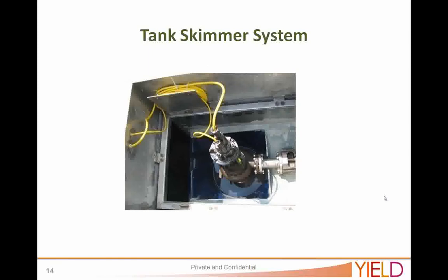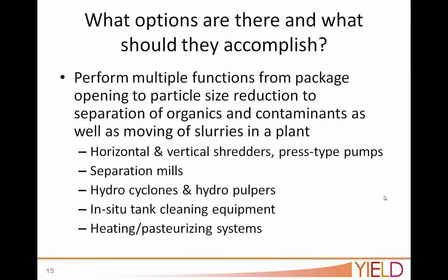And essentially all the digestate from the tanks passes through this skimmer and a filter. And so essentially every cubic meter that's put out of our system is essentially 100% clean. There is obviously still some grit fraction in there, but visible plastics are all removed, and you're into a small amount of grit, which is sand and particles like that at that point.